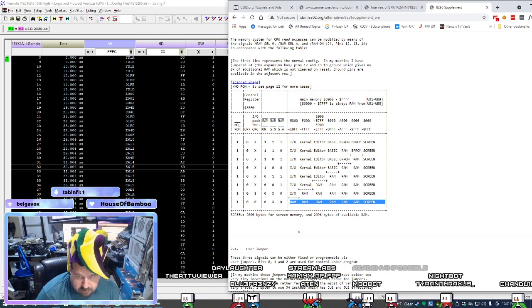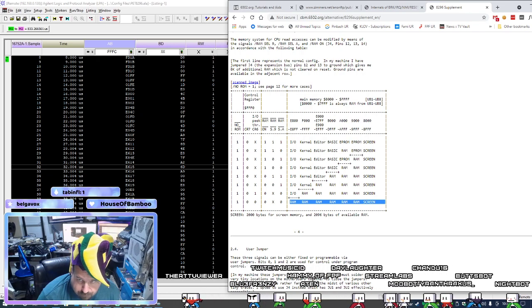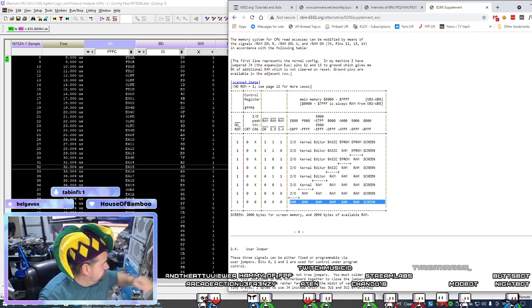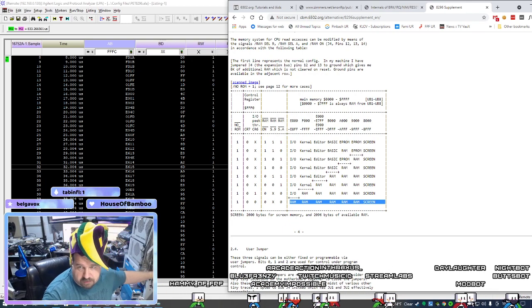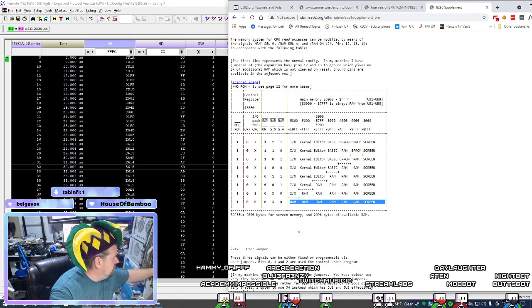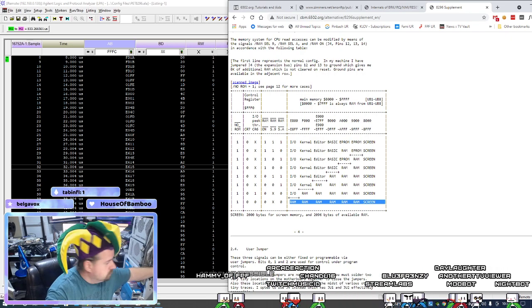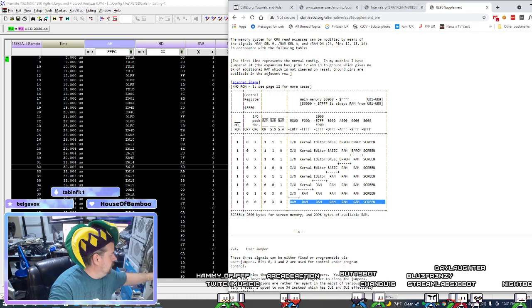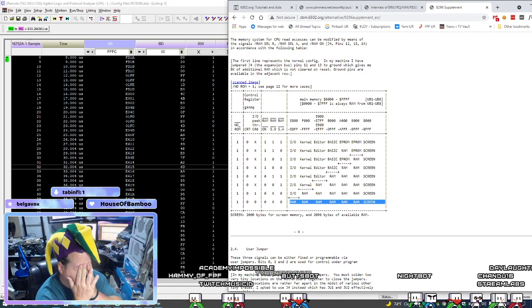So what I'm going to do is a RAM test at 8000, because the screen RAM is always mapped at 8000. I never check the actual RAM. So I'm going to do a RAM test of the video RAM and see if the video RAM is actually working.